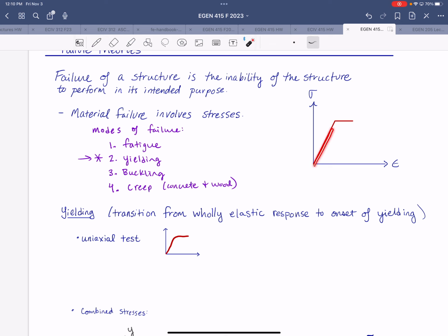A very idealized stress-strain curve just accentuates the point of yield as that location where you lose the modulus of elasticity, basically. I'm going to note that with a capital Y. The strain associated with that would be the yield strain.